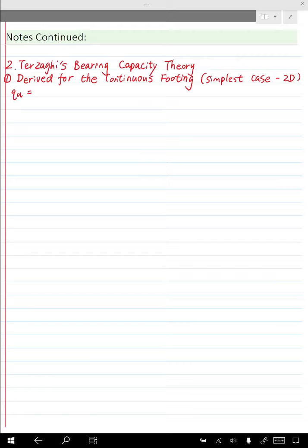One of the first things coming to my mind is that I can, for example, use the sand and put some glue in the sand, right? In that way, can the load be raised? You will say possibly yes, because it seems that the soil becomes more rigid. If we add some glue to it, the bonding between the particles is increased. So if we're talking about the Mohr-Coulomb criterion, by adding some glue to it,